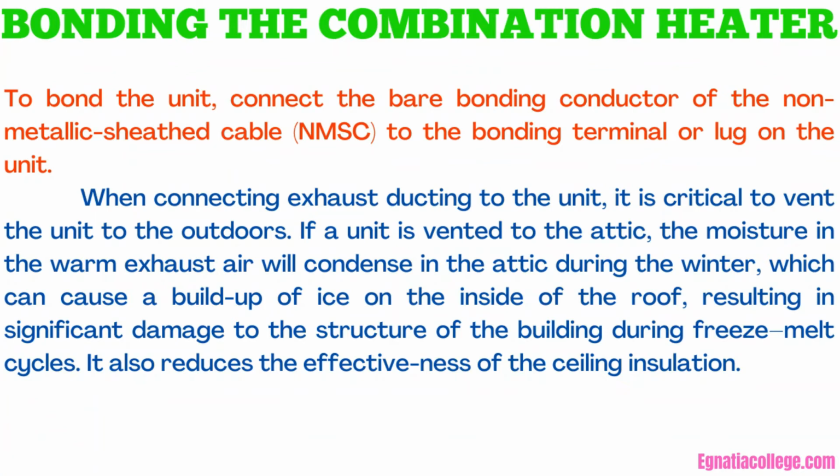Bonding the combination heater. To bond the unit, connect the bare bonding conductor of the non-metallic sheathed cable, NMSC, to the bonding terminal or lug on the unit. When connecting exhaust ducting to the unit, it is critical to vent the unit to the outdoors.